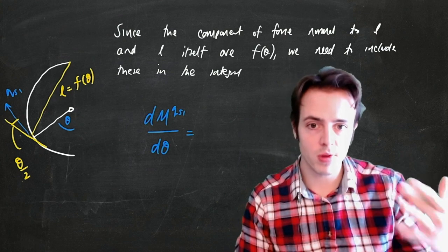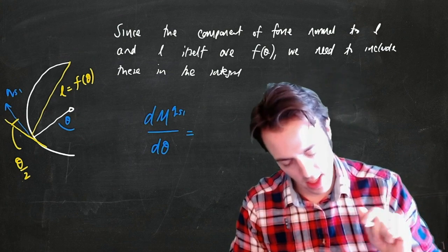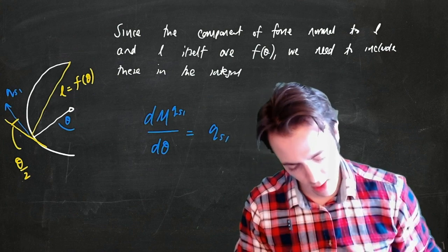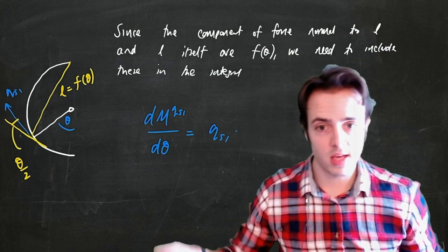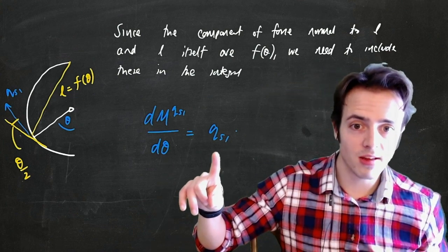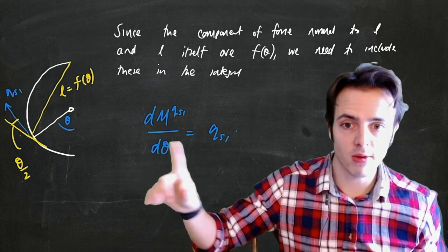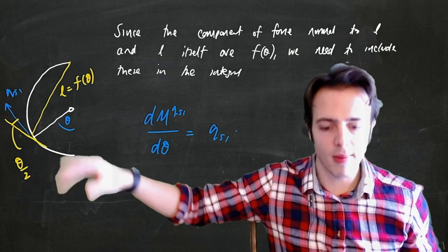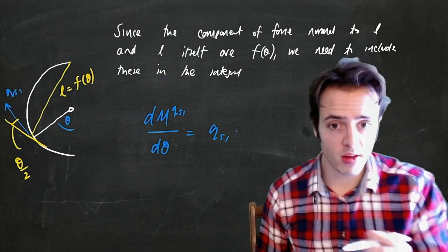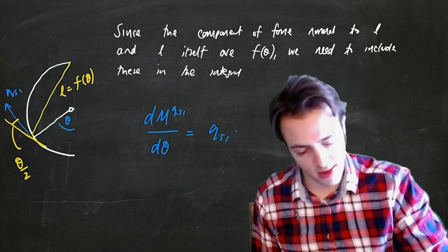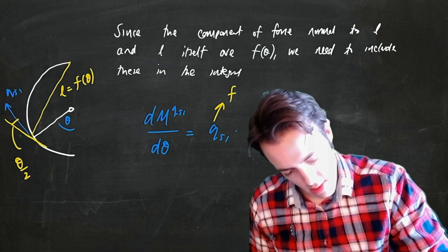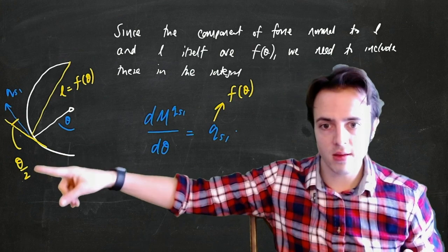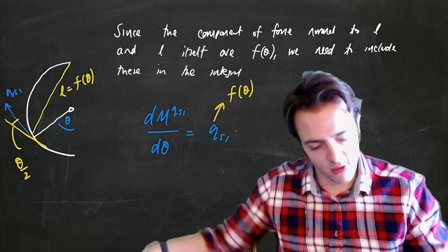So we're now looking at the contribution as the moment changes, is going to be equal to QS1, which is just, again, remember that shear flow is just newtons per meter, so it's force per, or newtons per elemental length. We've got QS1 as a function of theta, which we already have. So that's what we produced it as. We then need to convert it to this component here, so it's cosine theta on 2.